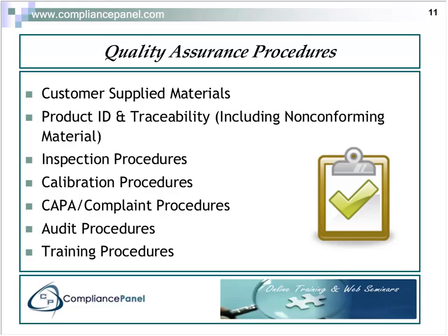Another thing to consider is the intervals at which these things need to be done. I've seen test equipment which you send out every 3 months, depending on how often it's used. You can put a system in place where you send it out every 3 months, and if it's not found to be out of cal, you send it out every 6 months, and if it's not found to be out of cal at that point, you extend again.